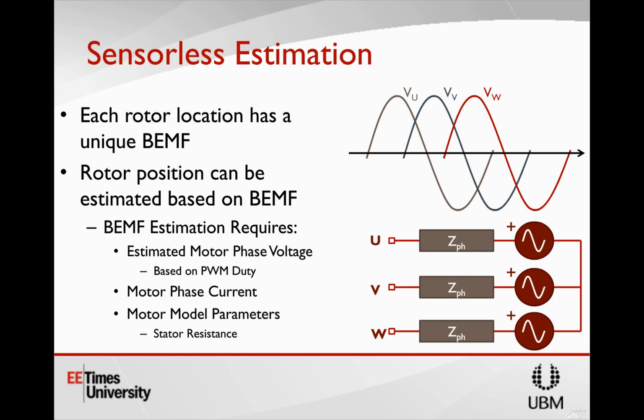For a BLDC application, you always have three half bridges controlled in a certain way, and the purpose is to control speed and torque, not really to reduce the ripple current inside the wire of the motor. So my first guess would be that this is not something that you can implement to control the motor. But I might need to reach out to Jeff directly because maybe his question has something more that I'm not understanding right now.